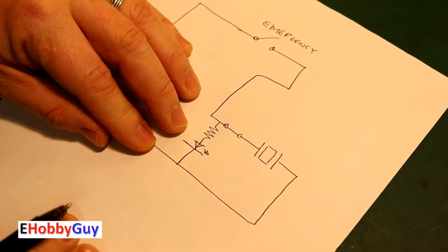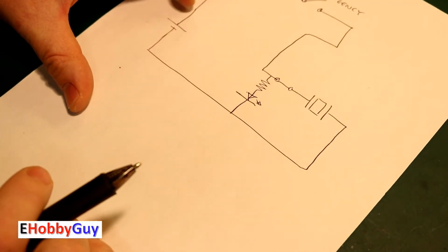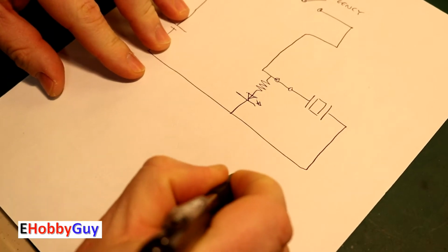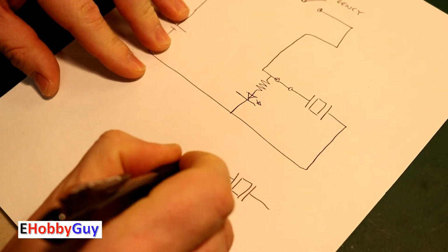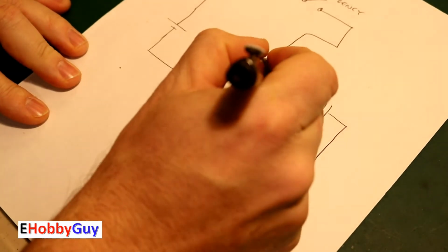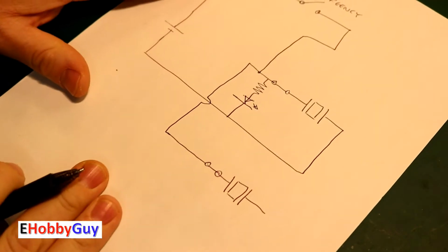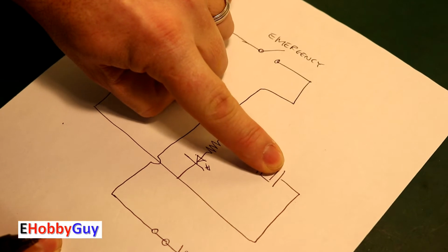What if we want it in more than one location, perhaps several locations? So let's see if we can add in a second location and bring it down further. I'm just going to draw the same configuration. Right here's a buzzer, and again, a normally closed switch. Upon closing this, we'll just tap into this when it does come down and bring down here. So right now from this switch we can bring down, it's going to set this buzzer off.